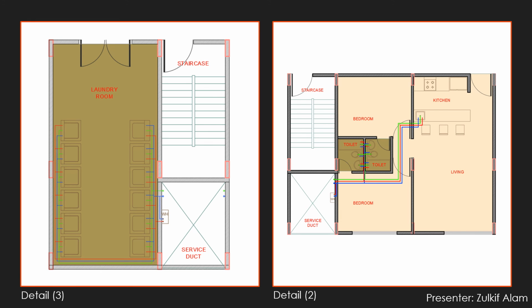In this slide, we'll be discussing the piping diagram for the laundry room and the apartment. The laundry room is designed for 6 washers and 6 dryers. All 12 spots are provided with a water line to allow for flexibility in the equipment placement. Each bathroom consists of 1 sink, 1 toilet, and 1 bathtub. The kitchens of each apartment have 1 sink but no dishwasher.